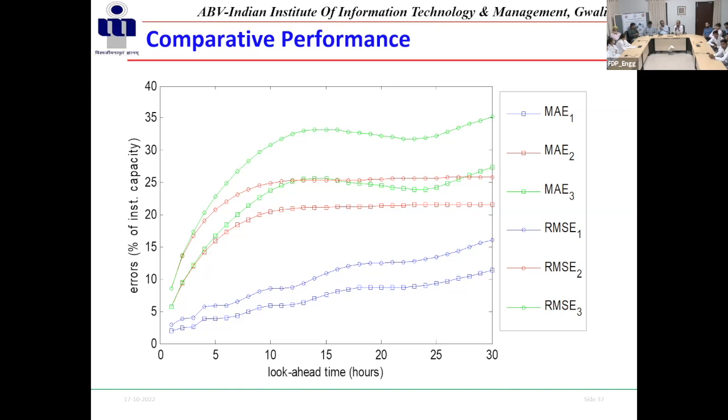I already asked my student about the maximum power transfer theorem: where do you use it in the electrical system? We never use it in the electrical system. Why? Because 50% is lost. The efficiency is 50% maximum for the maximum power transfer theorem. But electronics people use it because they are working in milliwatts. If you give 1 milliwatt and 0.5 is lost, it is of no value. But if 100 megawatts is flowing from a generator and only 50 megawatts arrives, you can imagine what will happen to the system. So for us, if the penetration increases, that error is very, very high.